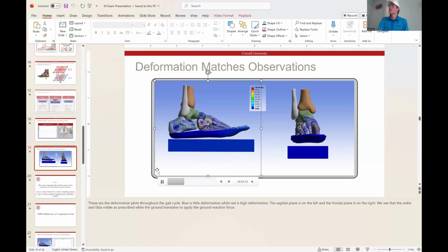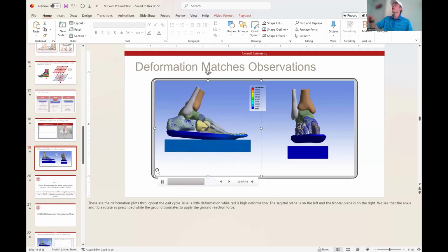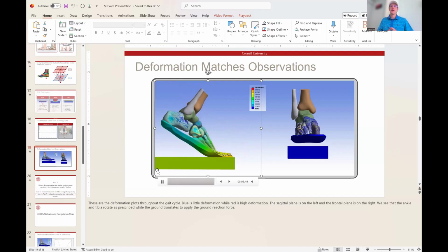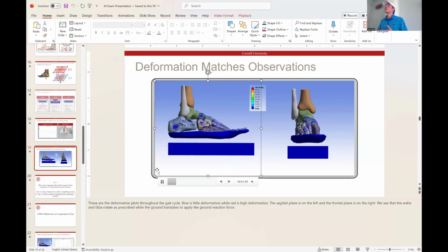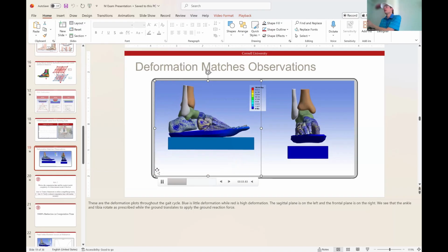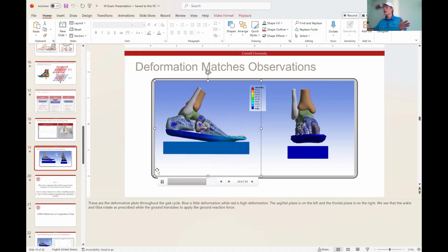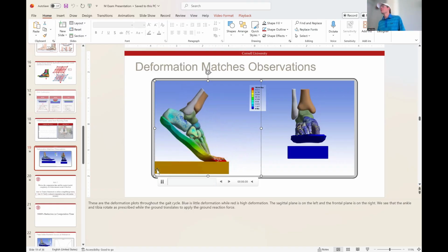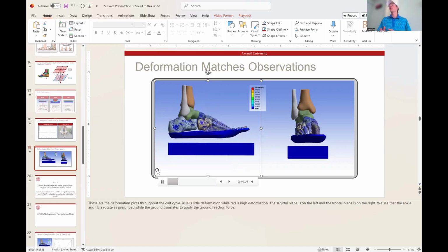A lot of the time is spent building the model, and then solving it. And when you actually take smaller time steps, say I used 5 load steps to apply loads, when I'm interpolating between these load steps, it's actually easier for the solver to solve, so it converges about the same speed.